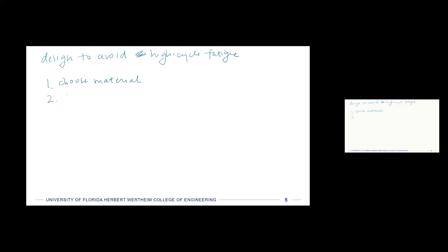And then find the most sophisticated set of these S-N curves you can for that material. That may be just room temperature, R. R. Moore data. It might be something more sophisticated from maybe a handbook. So the Machinery's Handbook will have a lot of these. And so you find the best set of curves that you can.